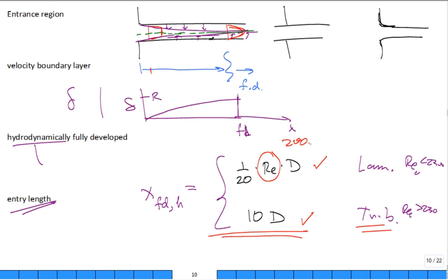So for laminar flow, this equation doesn't really work for anything greater than 2000, because if it's greater than 2000, isn't it turbulent? But let's take a look at some range of Reynolds numbers that are lower than 2000. Could you have a flow with 200? Could you have a flow with 20? It's a pretty broad range of Reynolds numbers from a maximum down. Oh, you could have a Reynolds number of 2, you could have a Reynolds number of 0.2, but let's just evaluate 200 and 20. Let's pick the 20, okay?